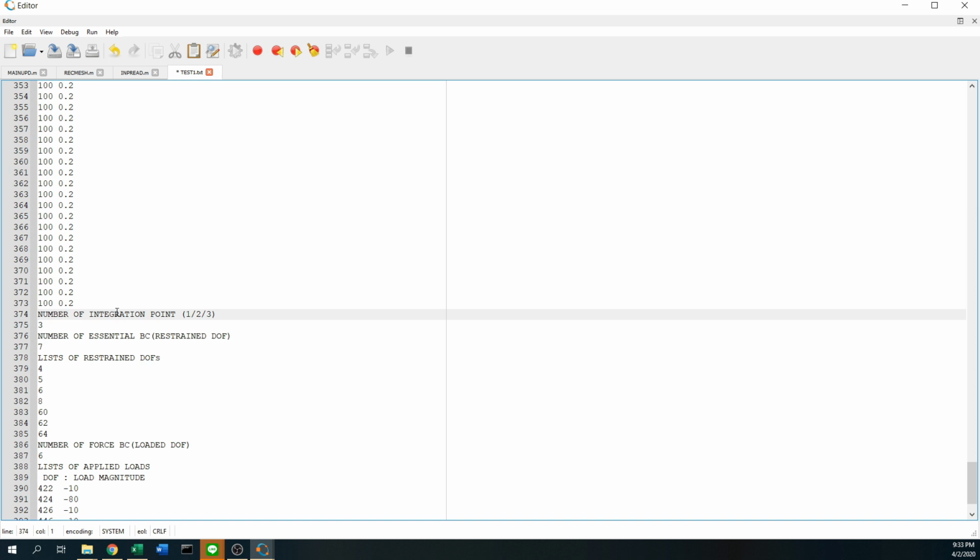So when you finish the construction of the domain, your physical domains on the model is there. You assign the boundary conditions, you assign the load, everything is already done. Then you gotta click to write the input file before you run. Okay, so you write the input file. It turns out to be the text file that you can open using WordPad, or even the simplest thing to open is the Notepad. So this is just the very simple input interface.